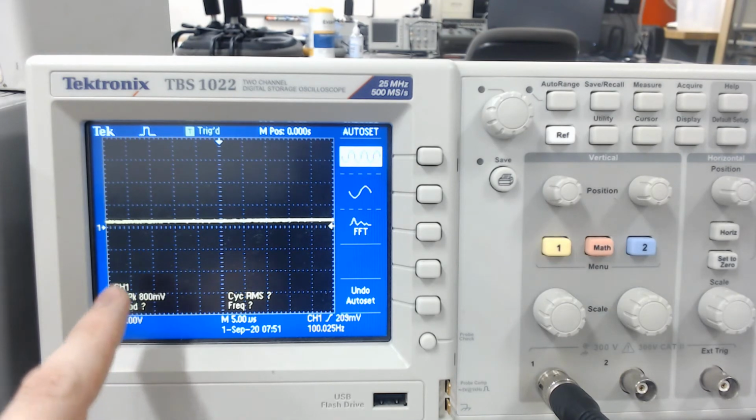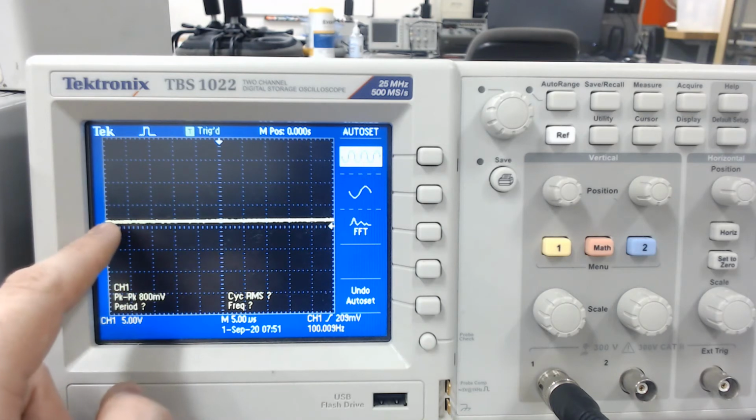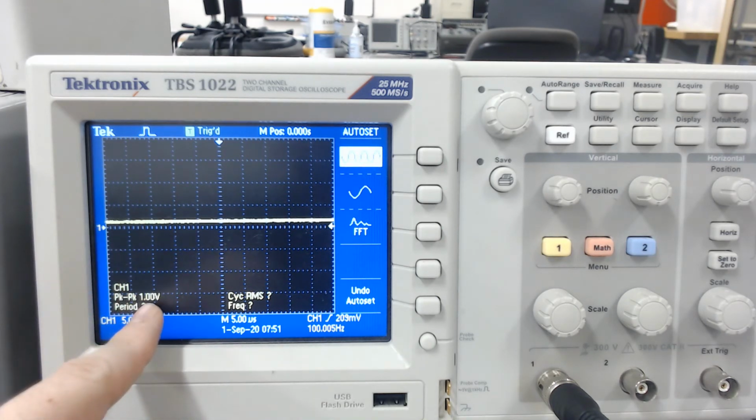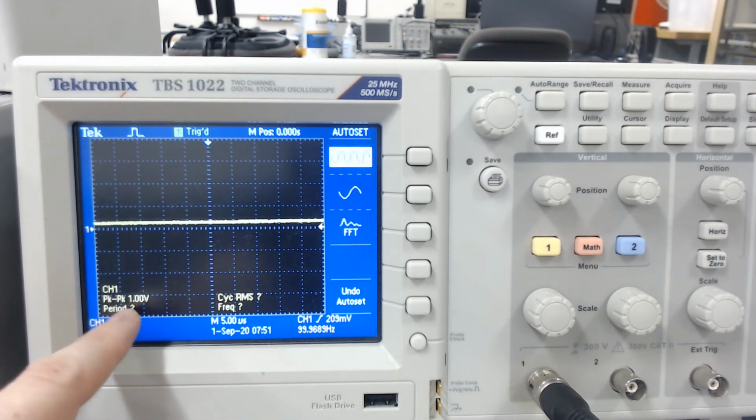And so basically what's happening is it is so zoomed out, so there's not much of a change from here to here, that the quantization error, which again we'll talk about later, comes into play. The oscilloscope has certain resolutions, and when it's so zoomed out and can't really see all the waves or what's going on, it's kind of just estimating it to be this, and so it's only accurate to 0.2 volts. So it keeps jumping up and down there.